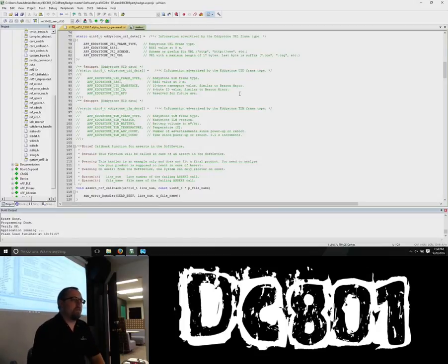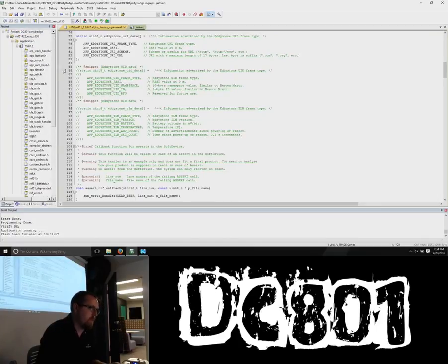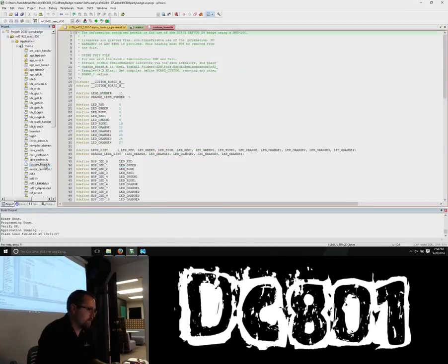Yeah, it's pointing to the .h file, the .h board file. So do you have a .h file that is named custom, board_custom? And so does that tell the compiler to use that file? Yes, it tells the compiler to use that file so it can program to your device that you have. Okay, so there's the custom board.h and then on the bottom there. There we go. So that's the file that you're defining in the C++ area. Yep. And this is all of the BLE information on all of the pins and everything, right?